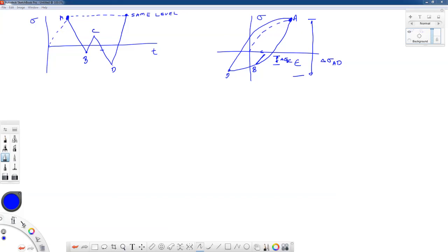Now we can take those particular stress ranges and plug them into our damage parameter, or look at our stress life curve if we're using that approach. We can find out how much damage each of those closed cycles accounts for. With this variable amplitude loading, the thing to remember is the material has what's called hysteresis, or memory.